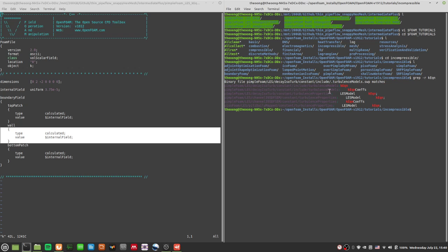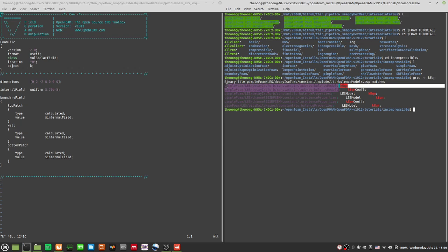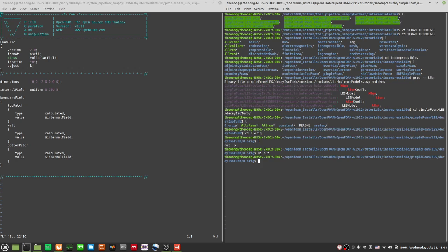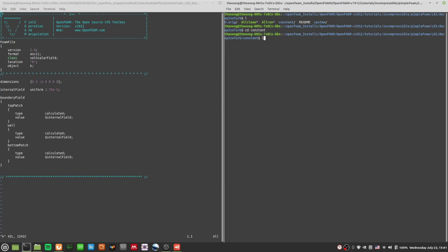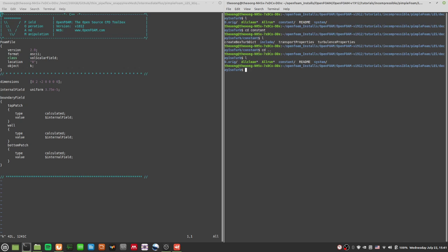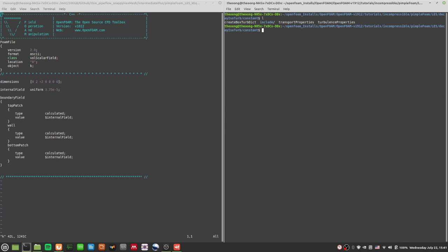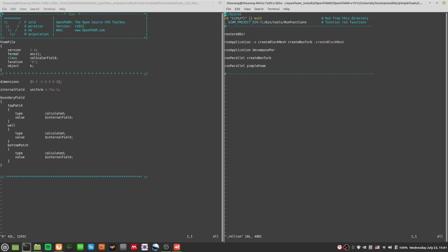All right. And you will see here, we just saw the decayIsoTurbulence case last time. That's one of the places we use that. We also see it in the turbulenceProperties. So let's take a look at this case to see what the case structure is like. We only have nut and p. Okay, looks like it's all cyclic. So it's not exactly a flow case, and it seems to be missing an entry for k, the turbulent kinetic energy somehow. And let's see if the Allrun here has anything.